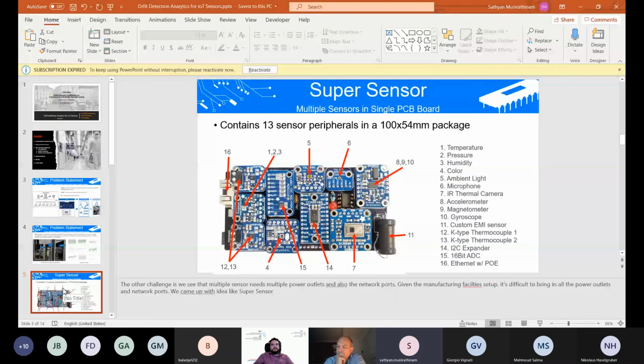It's hard to really collect the data in a real-time fashion. I didn't get into much detail here, but that's what we did, some sort of grouping. If we take an acoustic sensor or thermal camera, those are very high, at 48,000 samples per second, or 48 kilohertz. That's a huge volume of data coming through a different pipe than the low ones, like a pressure sensor, humidity sensor or temperature sensor, which is just 1,024 measures per second, right? So that's what we dealt with.